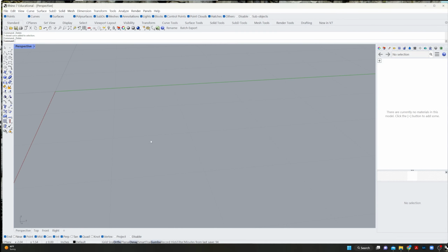I'm in perspective with the grid from the top down, and I'm going to draw a polygon. That polygon is going to be edge related. So I click on edge, and I'm going to do 1.25 because that's my dimension, 1.25 inches. Number of sides 5, 1.25, enter. Okay, and just to make sure, you notice I've got a straight edge here, which I like, that matches up with my grid, and I've got my object snap and ortho on here.